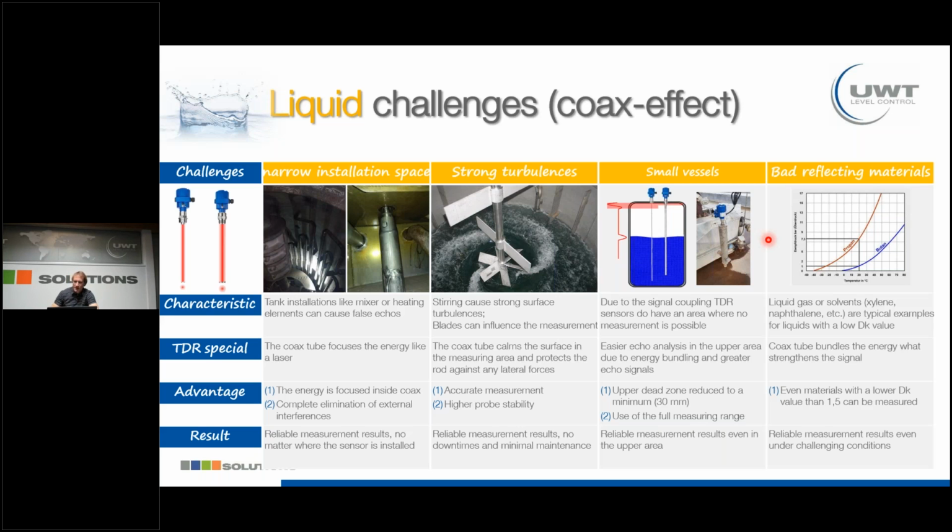Another effect is that due to this focused signal, we get an improved signal strength. The signal is better than when it's only spread around the probe. When we focus the signal inside this tube, we can also measure liquids with a very low decay value, like solvents or liquefied gases.